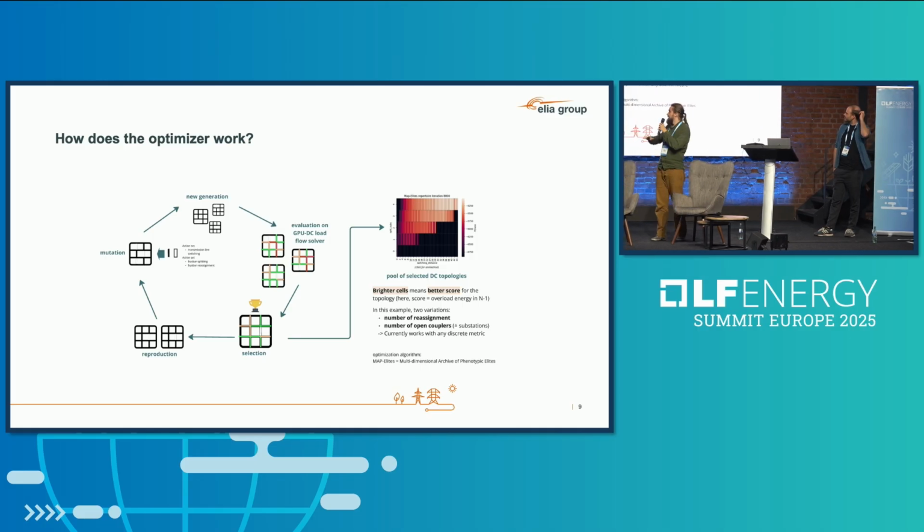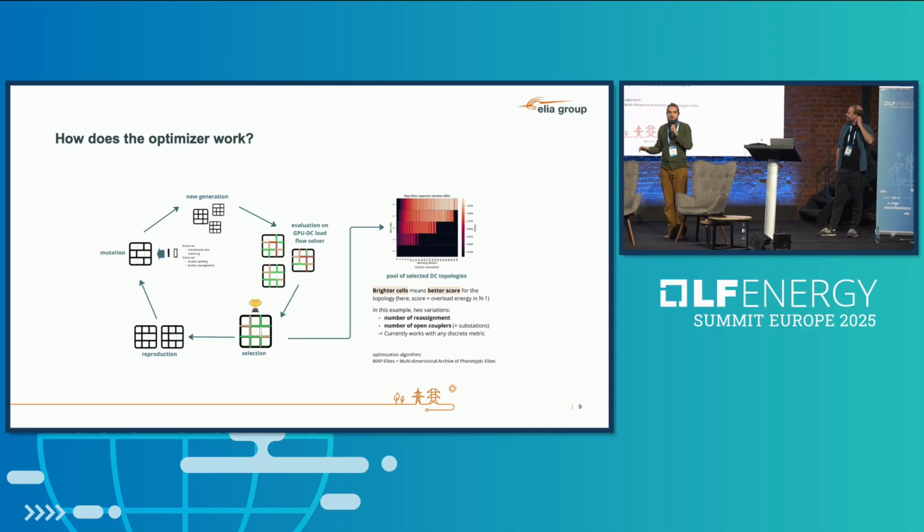But if I talk about quality diversity genetic algorithms, they're basically just a random search. We just randomly flick switches until something good happens. And yeah, this is not the strategy that you should do on the live grid, but in simulation we can do it. And because we can do this a lot, with 1 billion load flows per second, we can do a decent amount of topologies every second. We have the performance to search a large space of these 10 to the 120 possible candidates, large enough that we get a good solution most of the times.